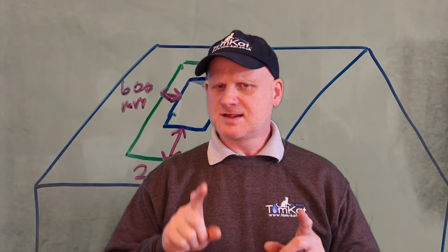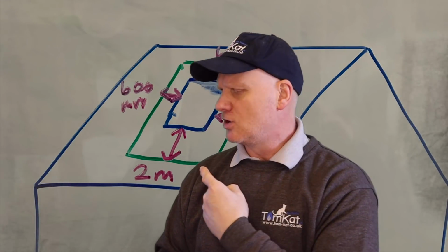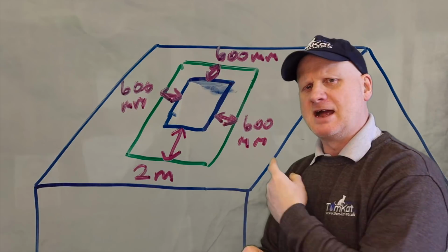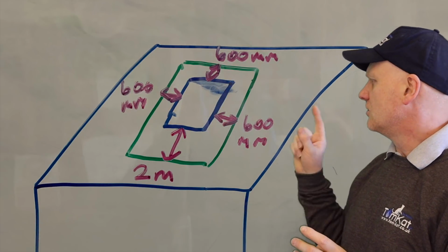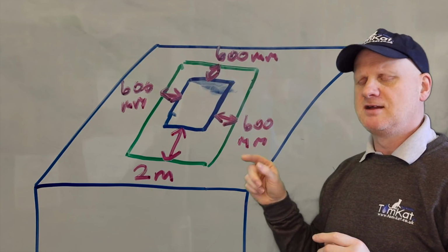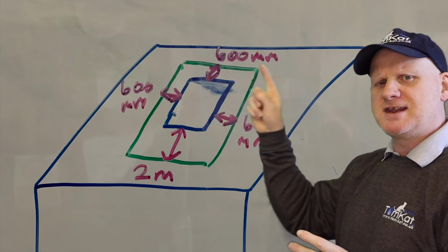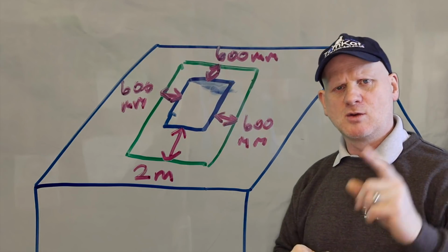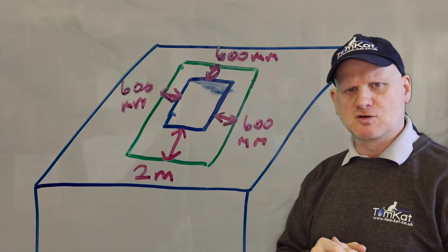Now, the main installation problem you're going to find with vertical flues is what's here behind me. Now, the biggest problem we've got is Velux windows. So you can see on the drawing here, the blue area is the Velux window. The shaded area around the window is the distances you cannot install the vertical flue to.